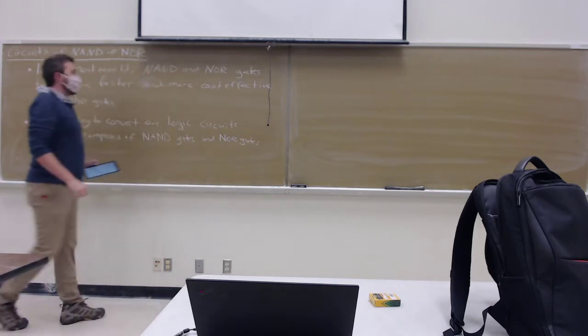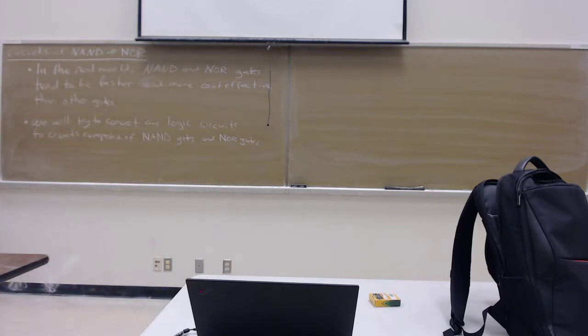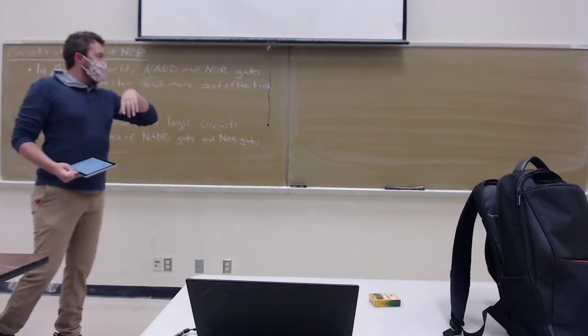And it turns out it's actually pretty easy to do. We'll do the thing that we've been doing, right? We'll get our Boolean expression from our truth table or our generalized min-term or max-term expansion.